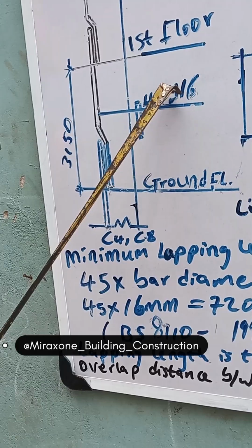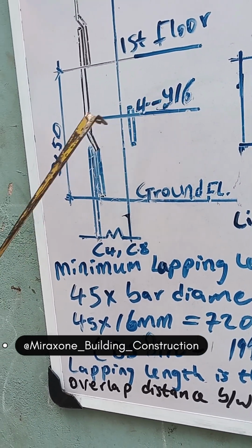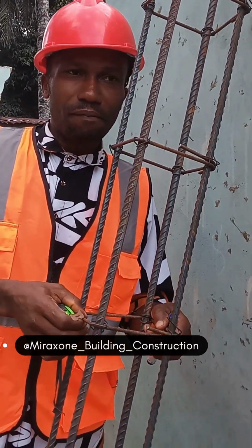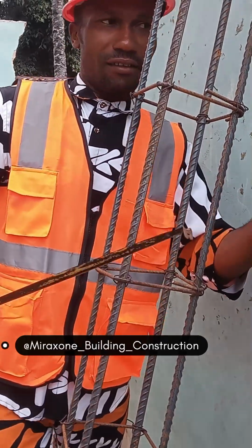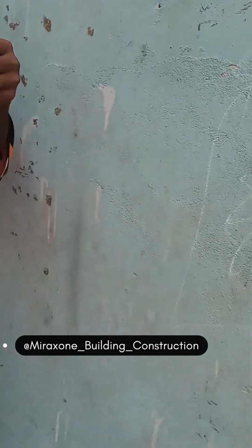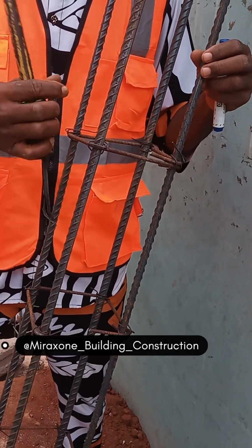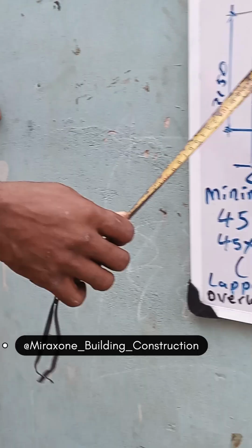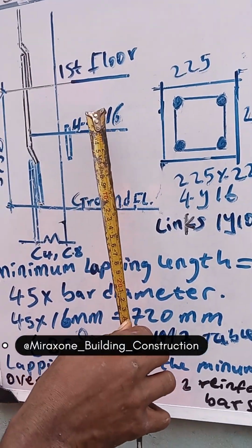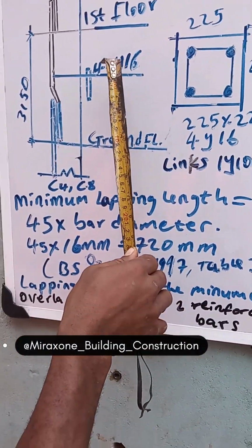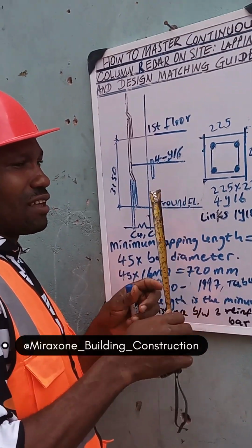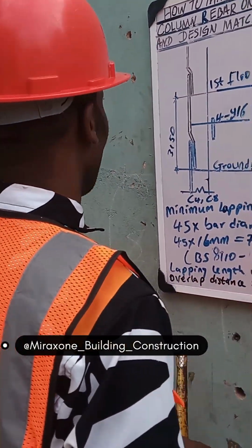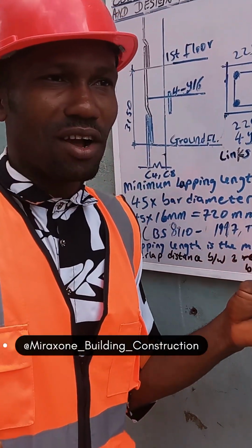So why here, zoom it, Y is the high yield type of reinforcement. The 16 here is 16 mm. This rod is 16 mm. So 4 is 4 bars. Y is the type of reinforcement being sold in the market, which is high yield. It has high yield tensile strength. The 16 is 16 mm, the diameter of this rod. I hope you have gotten it.